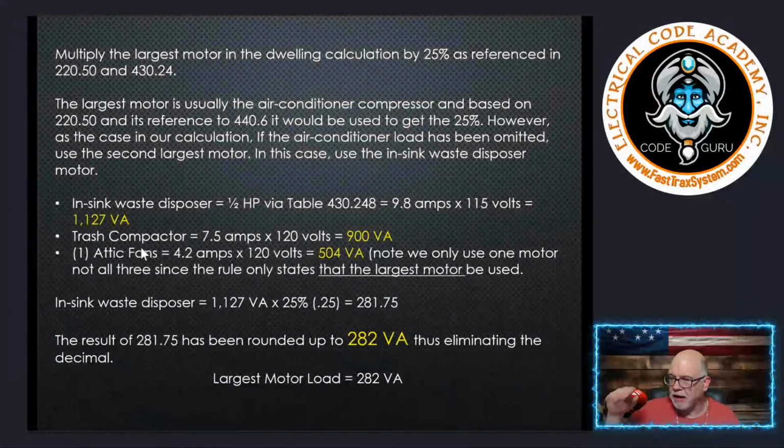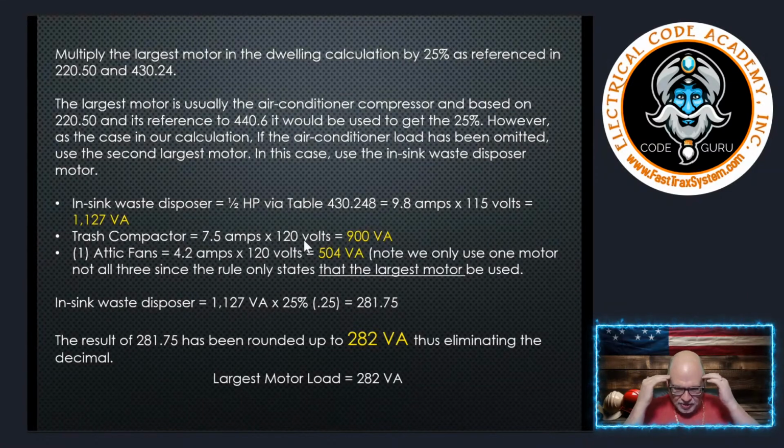Now, in our case, this is where you've got to think. Remember when we did the AC, which is the largest motor in the building, that air conditioning compressor? We compared AC versus heat. Well, guess what we did to that AC load? We got rid of it. We threw it away. We kept the heat. So we're not going to go after that air conditioning motor now. We have to go for the next largest motor.